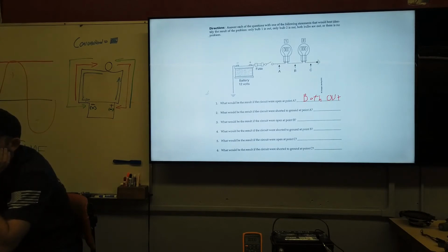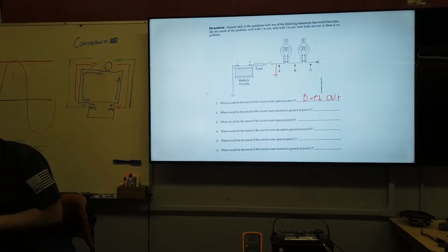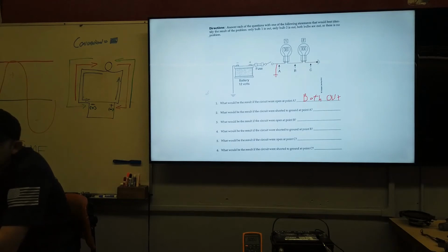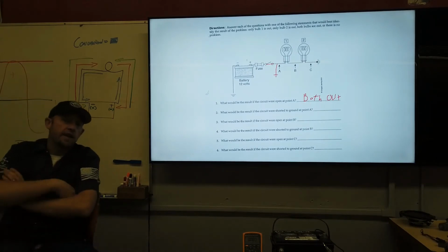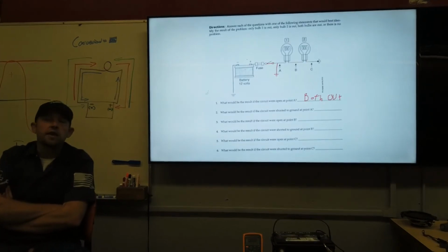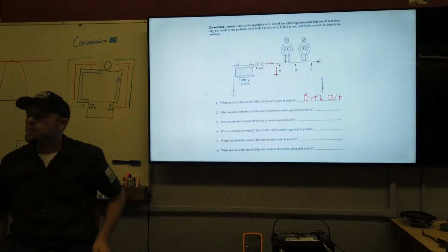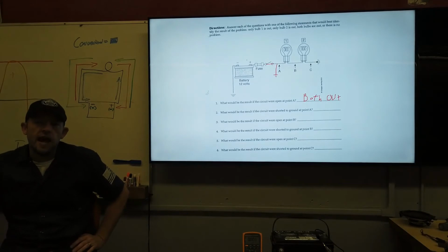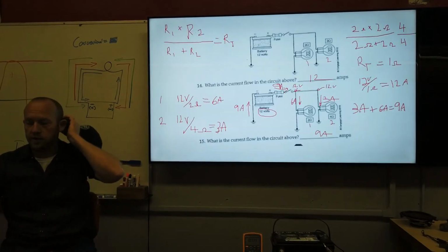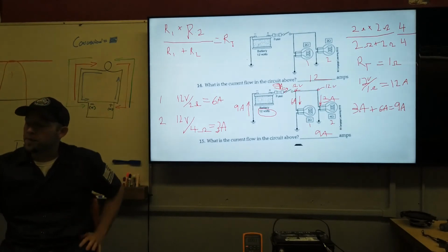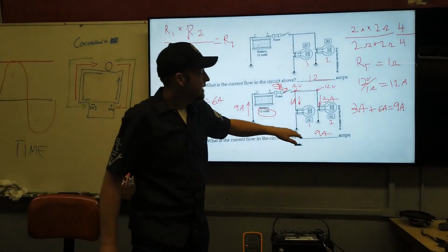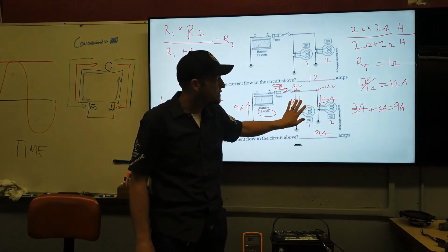So if I had a short to ground, then that would mean that I have a path to ground there. So even though this switch is shown as open, the understanding is that it can close. All right? So this part I want you to understand. You may have heard somebody say before that electricity always takes the path of least resistance. So that's a partially true statement. The truth of it is that more electricity will flow where there's less resistance. And so we see in this diagram that there's lower resistance here than here, so more electricity, more amperage, flows here than it does there.